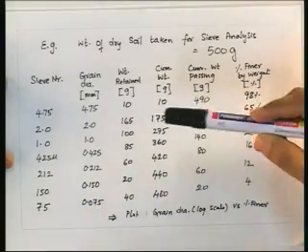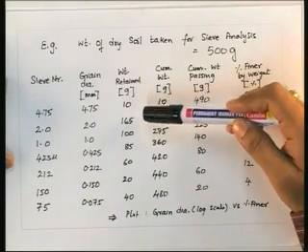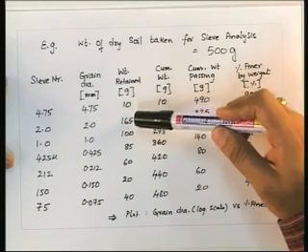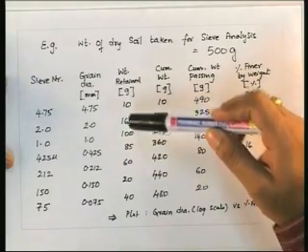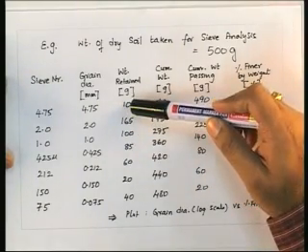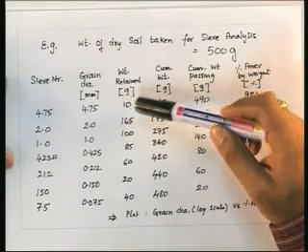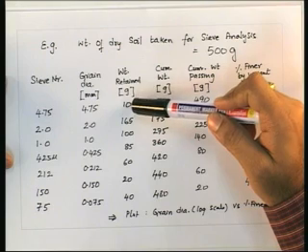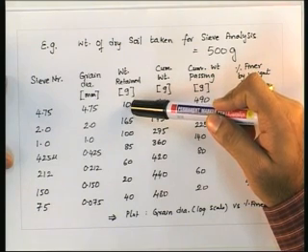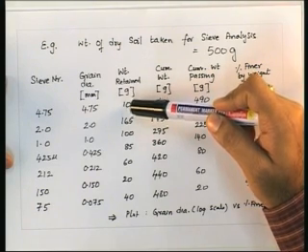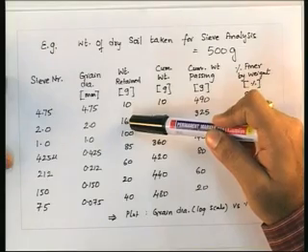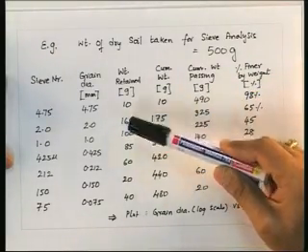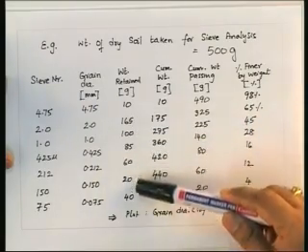Once subjected to shaking, let us say these are the weights retained in each sieve. For example, on the 4.75 mm sieve, the soil retained is 10 grams out of 500 grams. That indicates that 490 grams of the soil has passed through this particular sieve. Similarly, determine the weight of the soil retained in sieve number 2, and similarly through all the sieves.